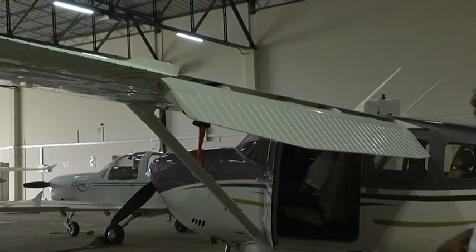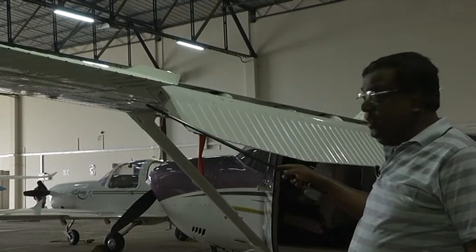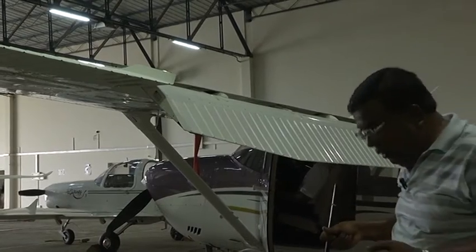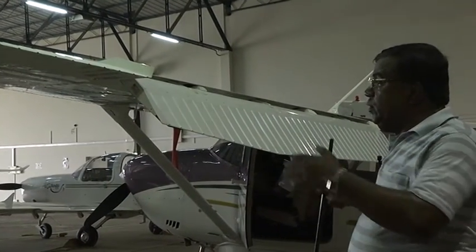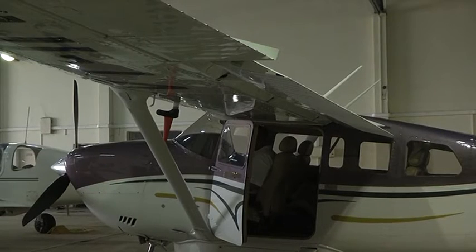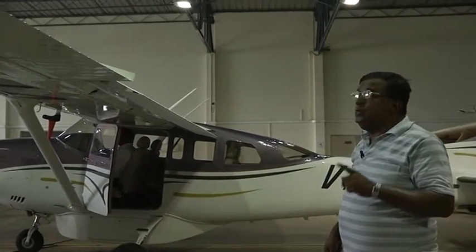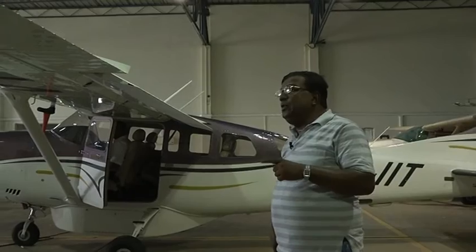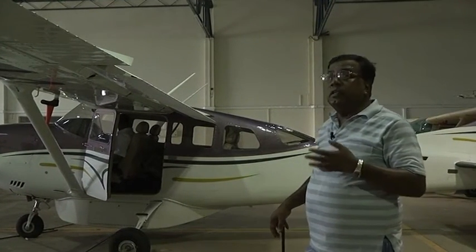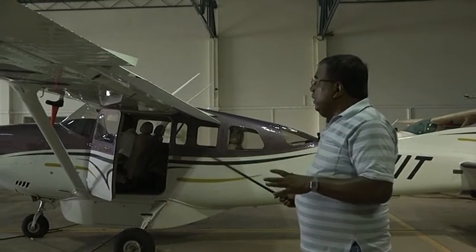And it's very evident now, you see, during landing when you are putting 40 degrees, primarily we are trying to increase the drag. That helps in braking the airplane to a shorter distance, because this is also important that we need to have a shorter touchdown distance, right? Please understand, when I say by putting the flaps down, we are increasing the lift, but that is at the cost of drag. So that is why in takeoff, we have to put a lot of throttle, almost power on. And the CL by CD max reduces, right? Okay? So this is the primary function for a flap.